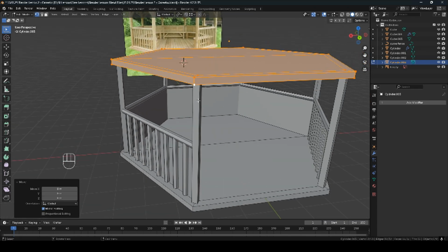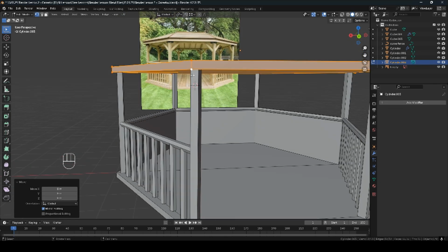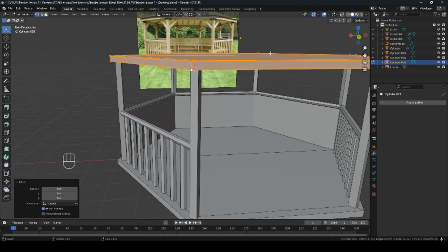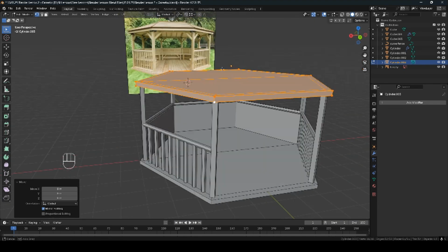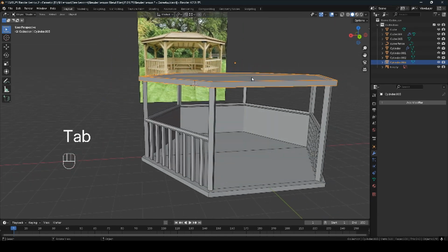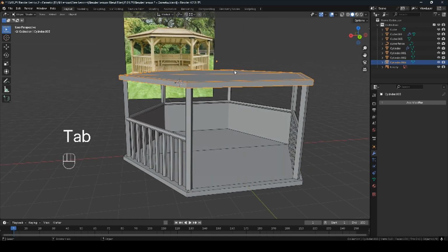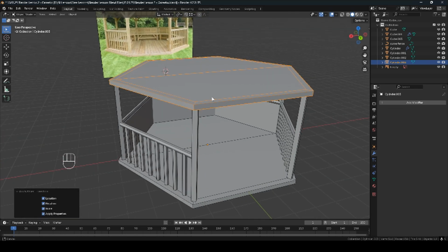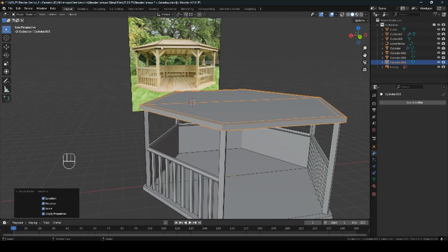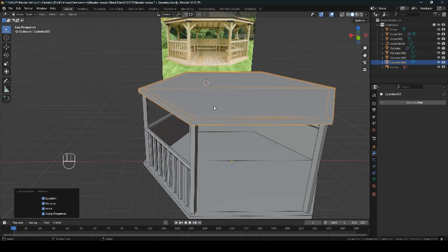Sometimes it can be a little bit tricky to get your head around because you select a tool and it's an active, and you're selecting that in line with something else you want to snap to, and then obviously it's staying on the Z-axis, so it's bringing everything down together if you have everything selected. As you can see, the origin point is floating in the middle there. We're going to reset that, so Control A, reset all transforms, and now it's gone back to the center. Now, as you can see, it's got a nice little roof on top.